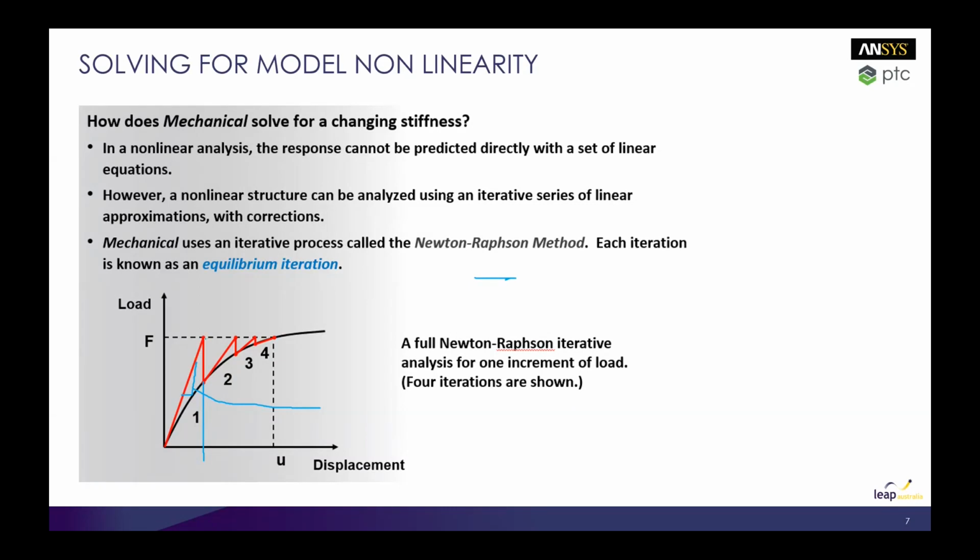sorry, this thing here is the out of balance. So based off that deformed state, we can calculate internally generated forces. So we keep repeating this procedure until the applied load balances the internally generated loads. That will come when we have a certain deformed configuration.